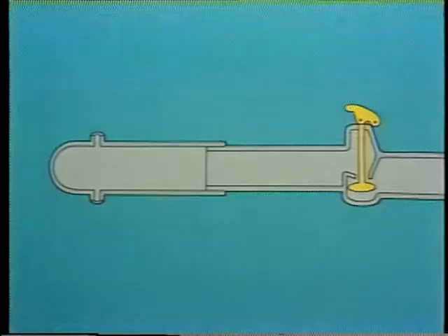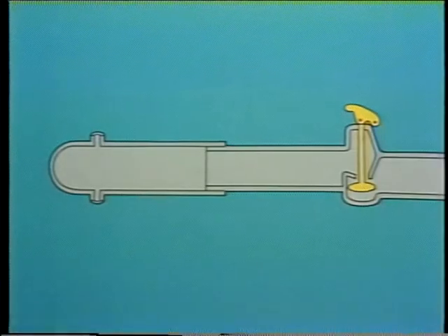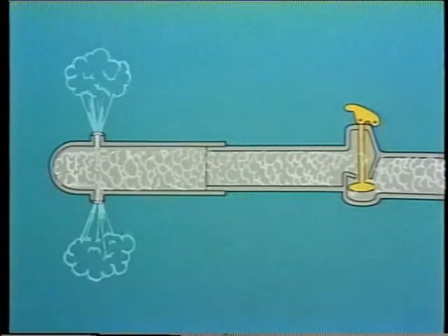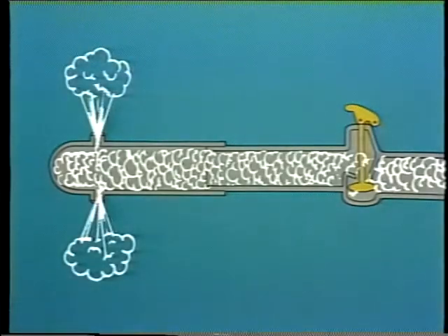So far, we've covered the 2 reasons soot blowers are used to remove deposits in a boiler. First, soot and ash buildup block the transfer of heat and reduce the boiler's efficiency. Second, deposits can cause damage to boilers both directly and indirectly. We've also looked at how a soot blower works and described the 2 types of blowing medium that are commonly used, steam and compressed air.